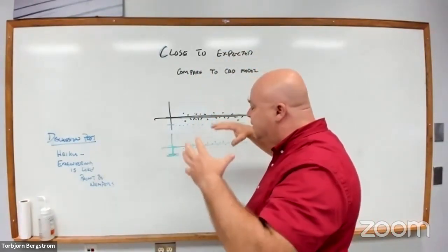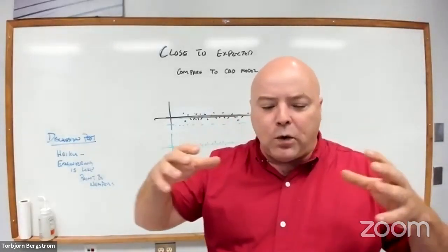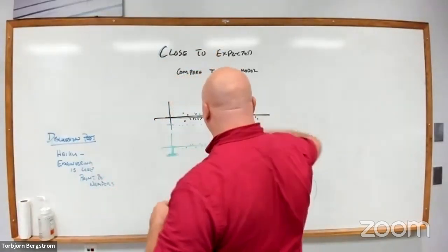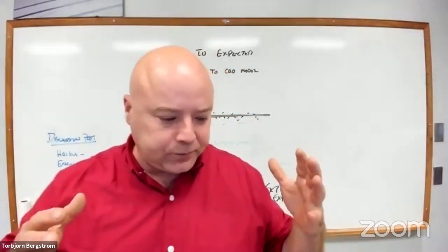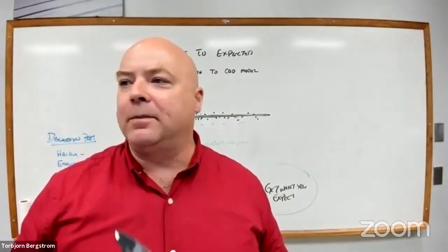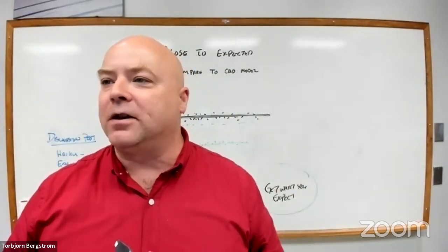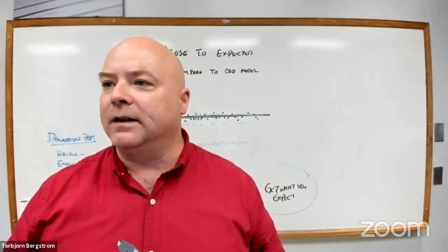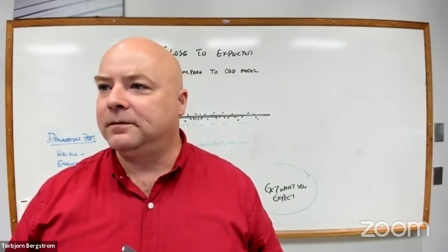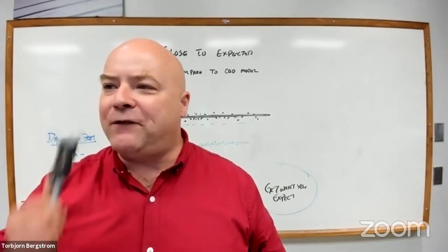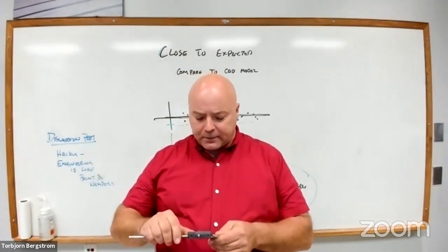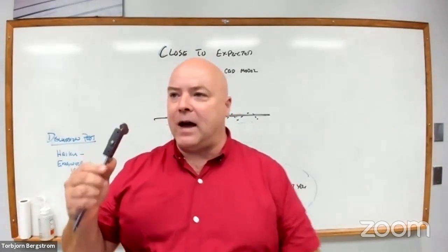There's measurement uncertainty contributes to how close we can be to having an accurate measurement. Now, if your measurement's all over the place, then maybe you need a better measurement tool. How, with my calipers, could I decrease the uncertainty very easily? The fastest and easiest way to decrease my uncertainty in my measured value. So these calipers will measure to 1/10 of 1,000th of an inch.